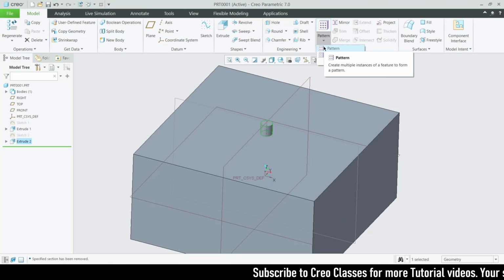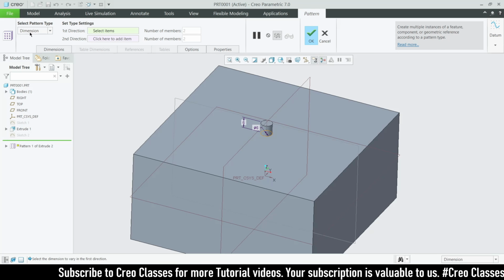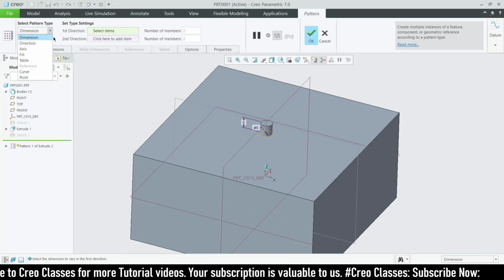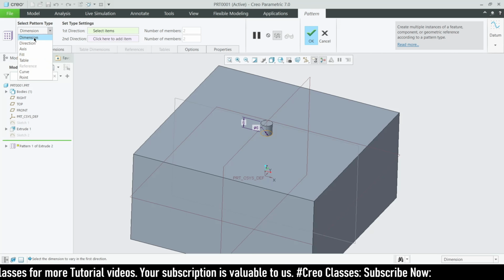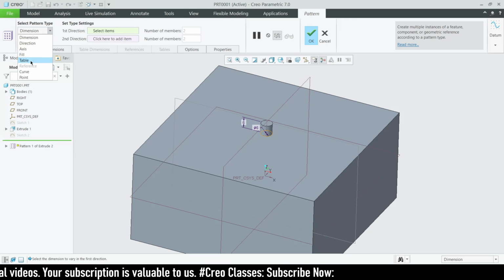Okay, so this is the main part which everyone will use. So first of all, pattern. When we enter into the pattern, you can see we have to select the pattern type. Let's see what types are available in this pattern tool. You can see dimension pattern, direction pattern, axis pattern, fill pattern, table, reference, curve, and point. Okay, so these are all the types of pattern available in Creo Parametric.